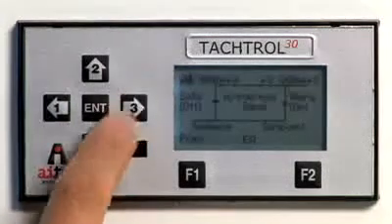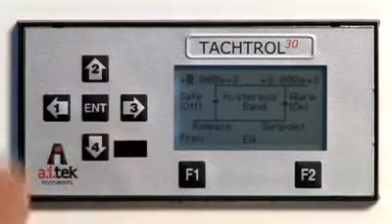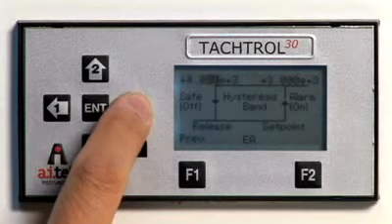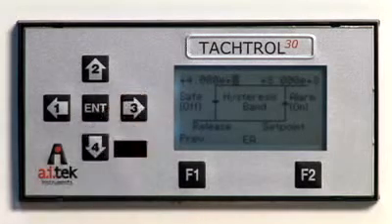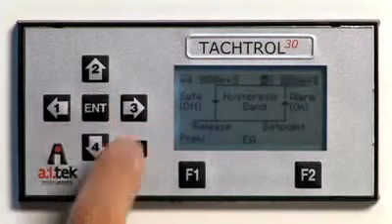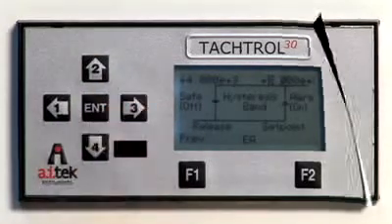Use the right arrow to accept the plus sign and move to the first digit. Using the up-down arrow, input 4. Move through the remaining 0 digits and assure exponent is set to 3. Press Enter to accept. Press the right arrow to move to alarm set point. Using the same procedure, set the first digit to 4 and the decimal digit to 5.